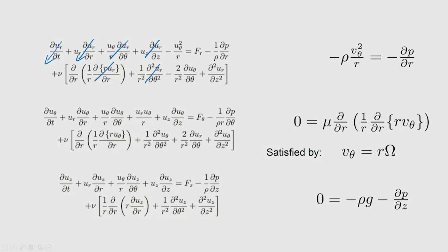So, I strike off all of those, and we also know that we have chosen the axisymmetric situation. So, we strike that off also, and there is no body force term along the radial direction. Which means that you have got only two terms, which we have indicated here as the first equation, which will give you the radial variation of the pressure.